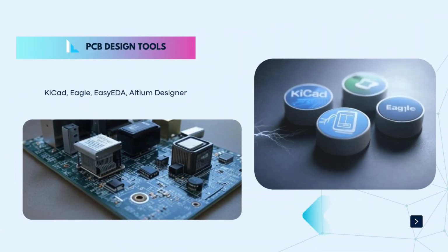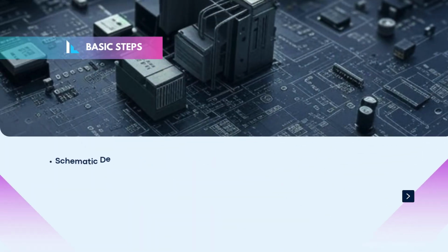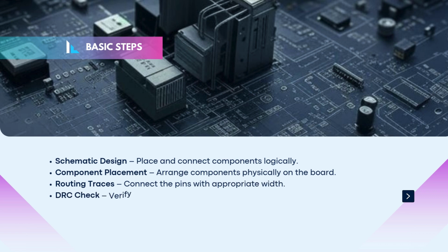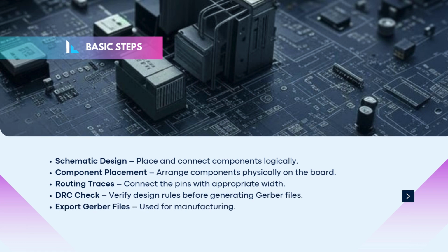PCB design tools: KiCad, Eagle, EasyEDA, Altium Designer. Basic steps. Schematic design: place and connect components logically. Component placement: arrange components physically on the board. Routing traces: connect the pins with appropriate width. DRC check: verify design rules before generating Gerber files. Export Gerber files, used for manufacturing.